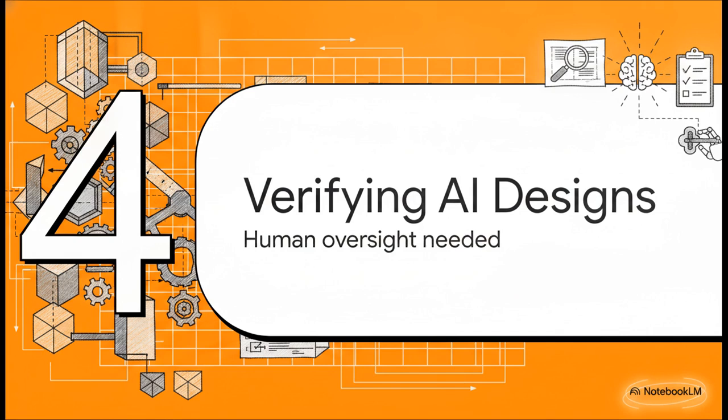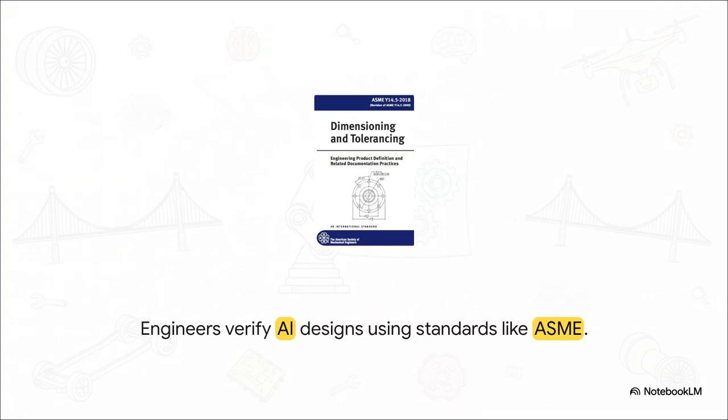All right, let's look at Section 4, Verifying AI-Generated Designs. Because let's be real for a second. As amazing as AI is, it's not infallible. While AI can automate rule checking against vital standards like ASME Y14.5 for dimensioning and tolerancing, the human engineer must still take final responsibility. You have to verify the specific loads, confirm your boundary conditions, double-check the material properties, and ensure the safety factors are actually appropriate for the real world.